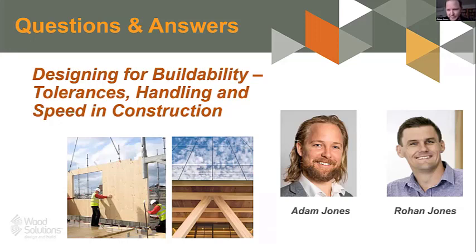Yeah, so I'd say it's just something that you need to design for, like any material, no different to multi-story concrete buildings. Understand how much it's going to move and make sure we're accommodating that within the connections. And also look at how we do our panel breakups. Rather than having, say, a continuous panel connecting into the core where you have additional stress, you can make sure the panel breakup allows for that additional movement to take away the concentrated stress from the connections. Look at slotted holes. Like anything, we need to understand how much movement there's going to be up front and design for it accordingly.